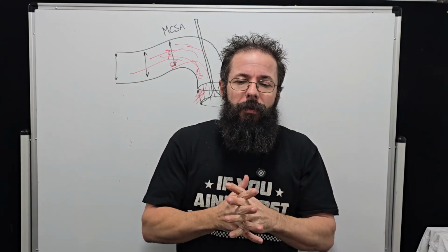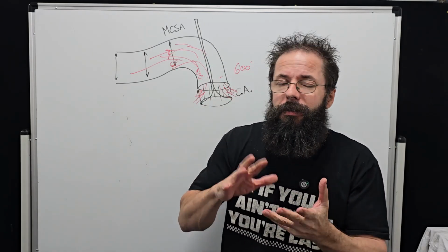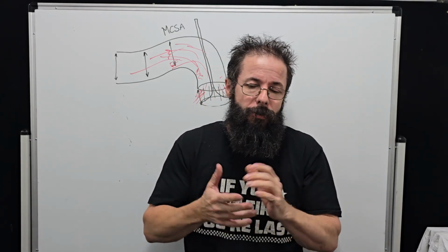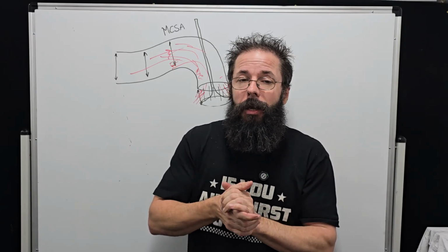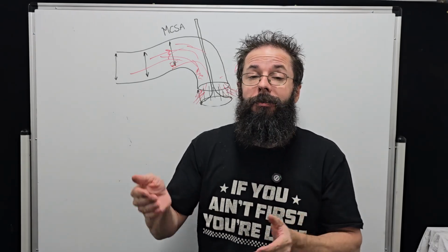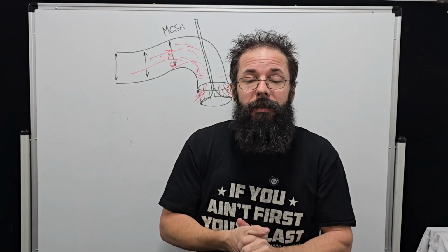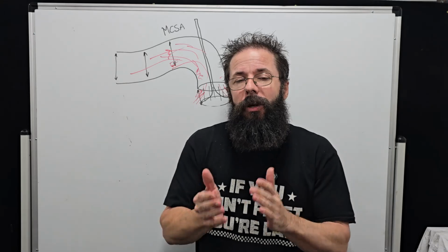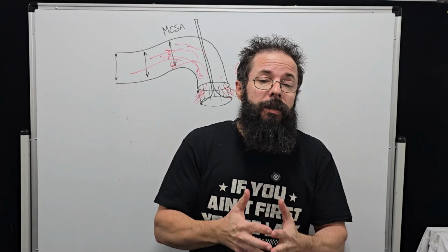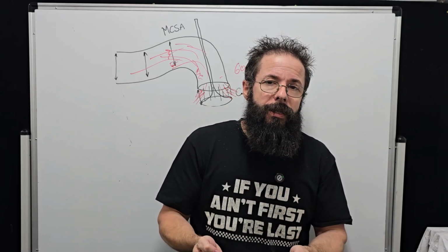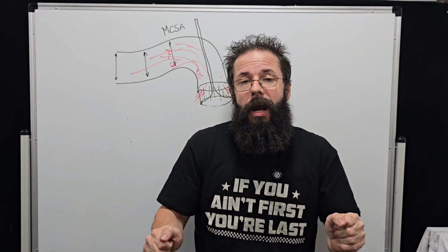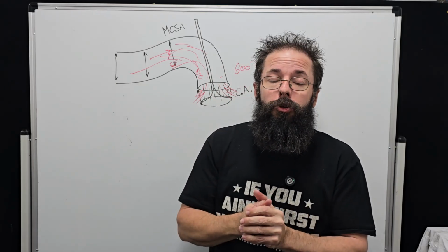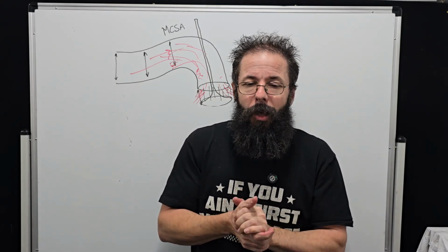Again, with a 2-valve, there's roughly an 80% rule. Again, it really depends, sometimes more. So with the 4 valves, I tend to like bigger minimal cross-sectional areas, so lower peak velocity, that dynamic element that we would calculate, and better average velocity across the port. And a lot of the early 90s ports were absolute trash in the 4-valve scene as far as two intakes go.